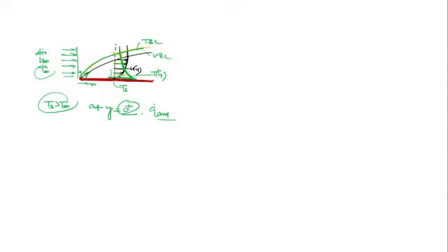Then it is in series, meaning whatever energy gets transferred through conduction at the wall, at the same rate that energy should be propagated by convection in the fluid, because now the fluid is in motion far away from the surface of the solid. So can you say at y equal to 0 plus, q conduction equals q convection?